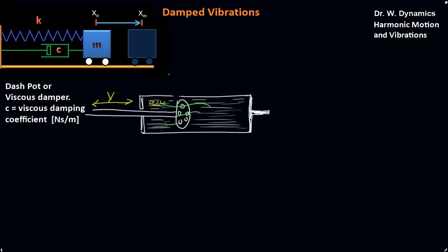And our equation will be that the damping force, Fd, is minus cv. It always acts opposite to the velocity because we have a buildup of pressure back here as it tries to squeeze past, and it's linearly related. As we increase the velocity, the damping force increases linearly with respect to that. So a shock absorber is a good model for viscous damping.